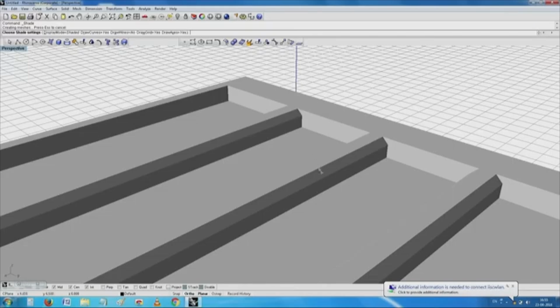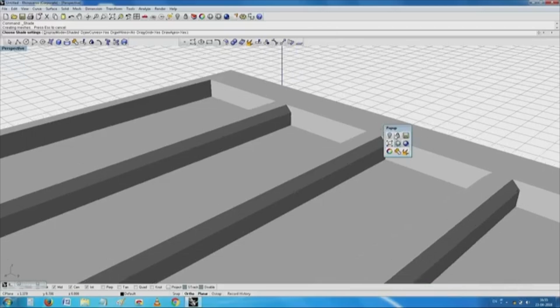The advantage is, because there is material here, there is no point in that nozzle going everywhere here. So, logically probably the nozzle moves one length and then moves over to that and moves and so on, depending on the manufacturer's capability and the type of technology at that moment, they will make an optimized way of building these things. So, no material is deposited here. However, material was there and this next layer needs to now follow up, and getting this corner is a tough job,